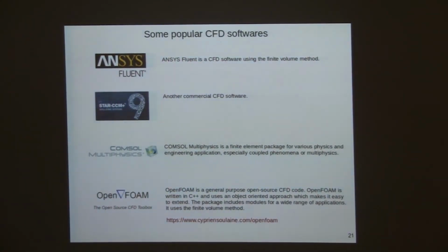CFD software. Some are commercial, like ANSYS Fluent or StarCCM+. You also have COMSOL. These first two use the finite volume method, and this one uses the finite element method. And you also have some open source simulation software. OpenFOAM is becoming more and more popular. It's known to be the open source equivalent of ANSYS Fluent.